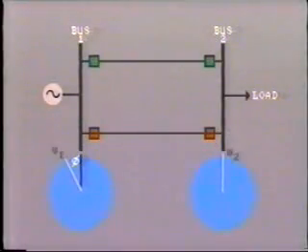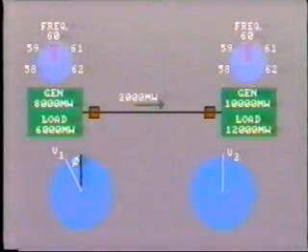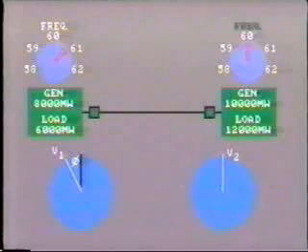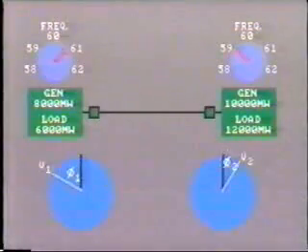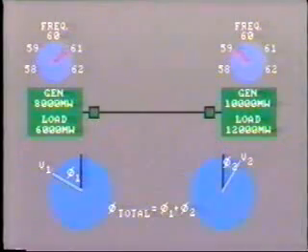When automatic reclosing takes place, it is essential that both ends of the line remain in synchronism, or at least close to synchronism. This may not be the case, for example, with an interconnecting line between two power systems. If there is a large power flow over the interconnection before tripping occurs, it's likely that the two systems will rapidly move out of synchronism when separated. One system may speed up, while the other decreases its frequency. The phase angle between the two systems will increase rapidly, and they will not remain in synchronism. In this case, automatic reclosure cannot be used.